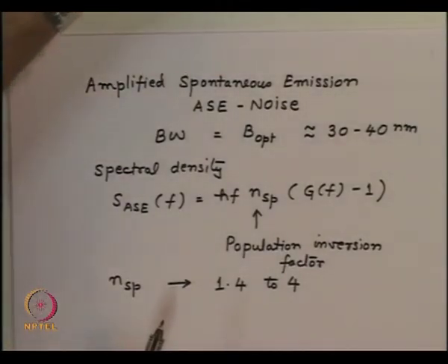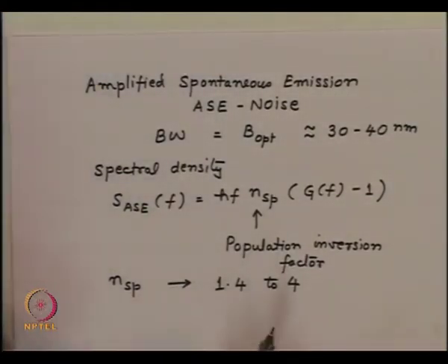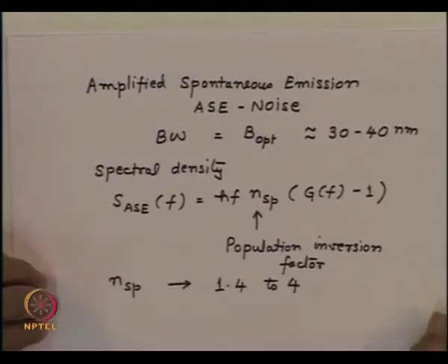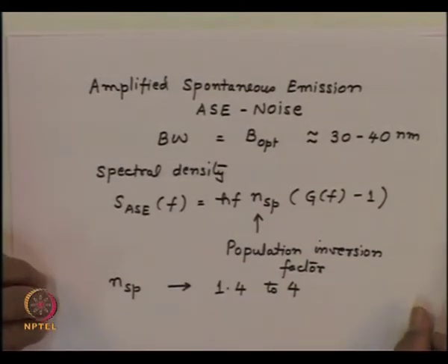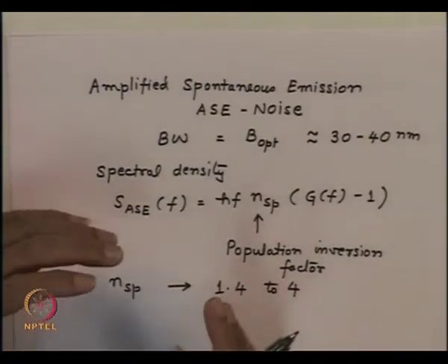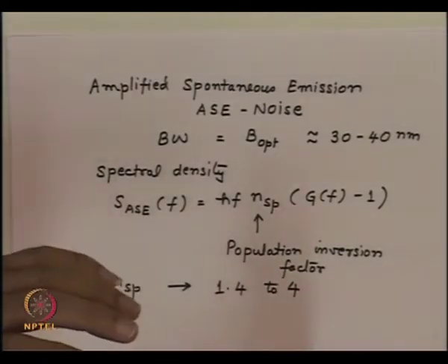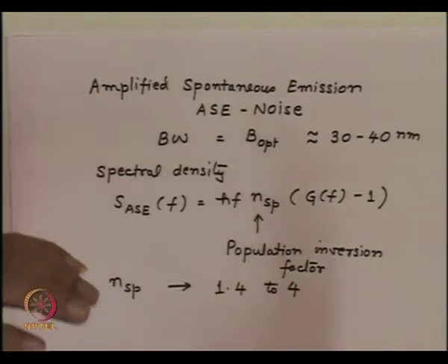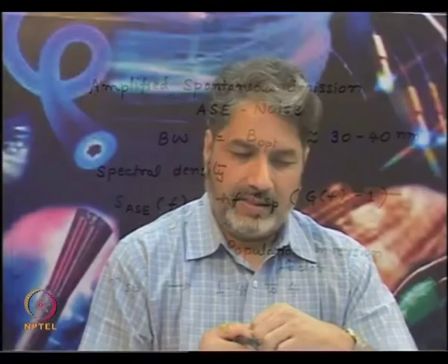So essentially then one can get the amplified spontaneous emission noise, or ASE noise, and this also depends upon which way the amplifier is pumped. In fact, the reason we talk about two different schemes, co-propagating and counter-propagating, is because the ASE contribution is different in the two cases, and that's what is shown here.